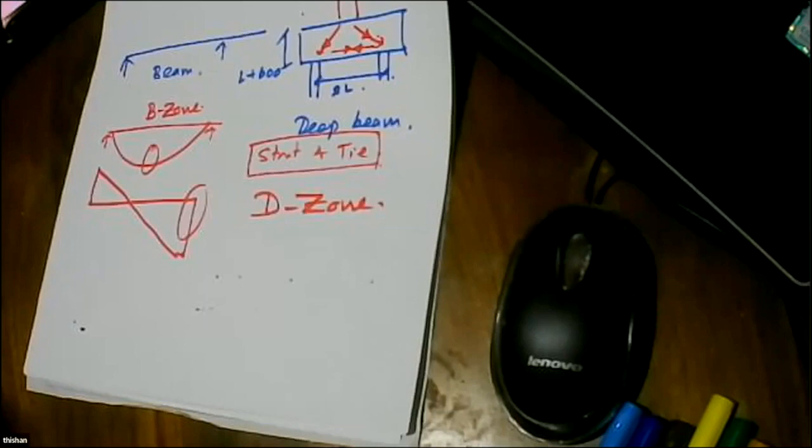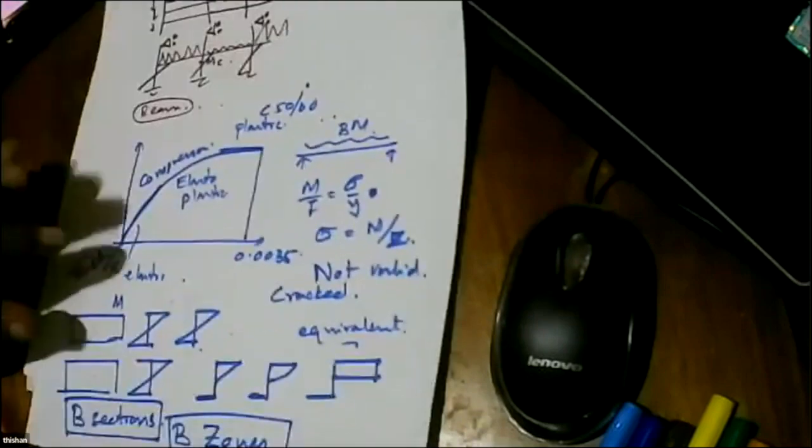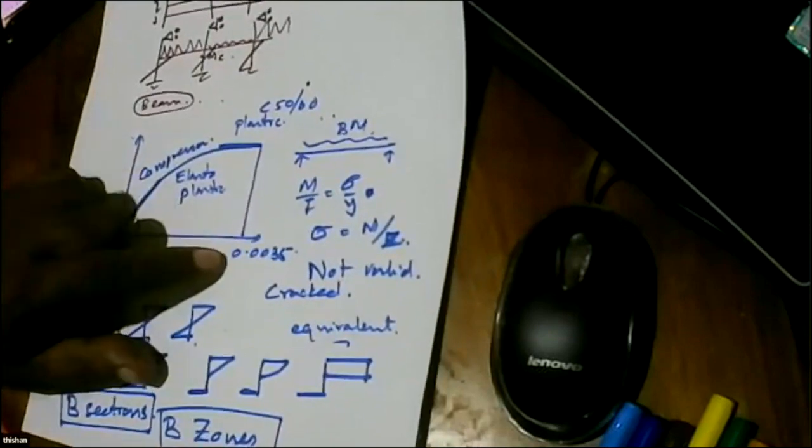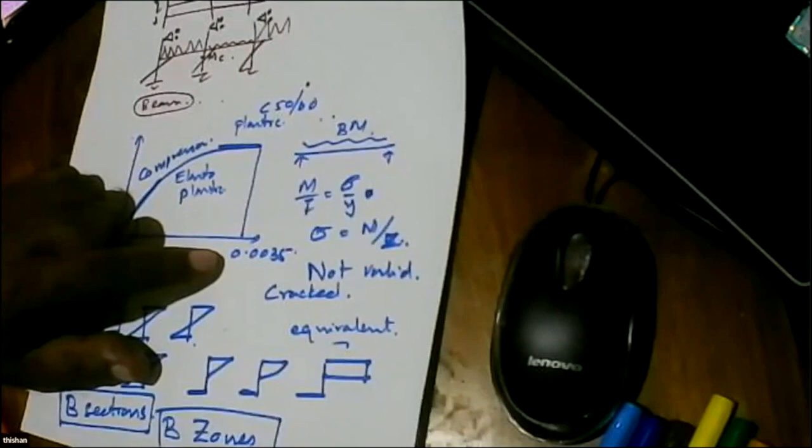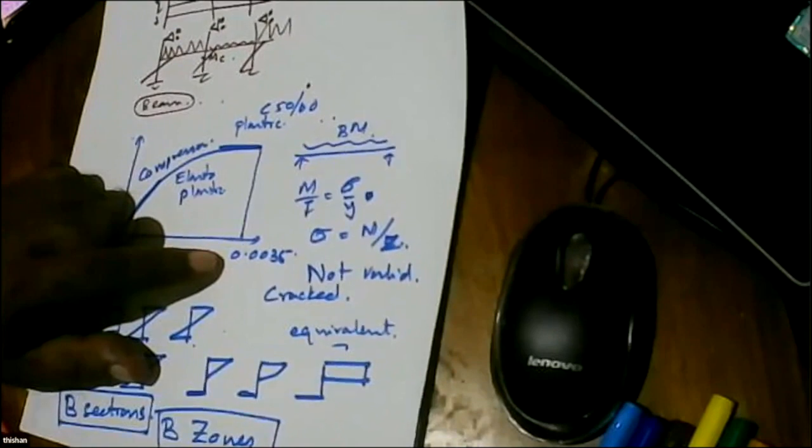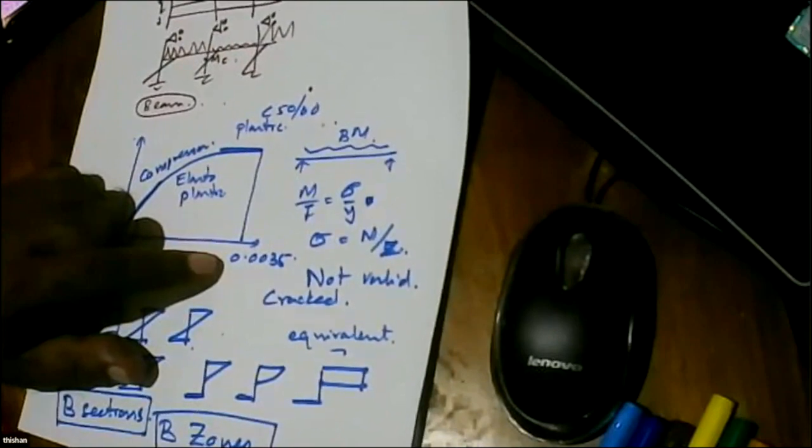For example, even in the same Eurocode, for less than 50 megapascal, 0.003. Greater than 50 megapascal, 0.0032, 0.028, different values are given. So these values can vary from country to country. So that's why some flexibility is allowed in the codes by developing national annexes.